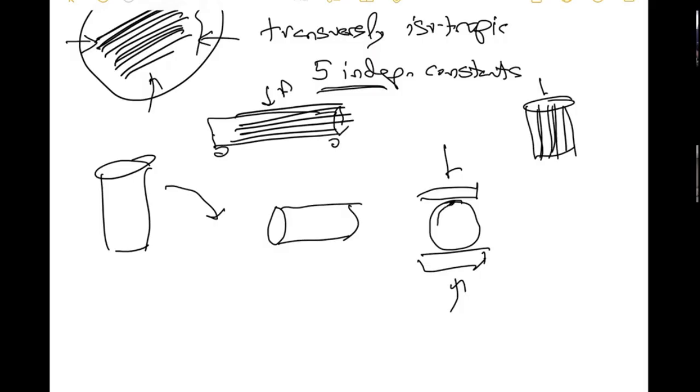So you end up getting the forces are flowing kind of like this. And so the result is you can solve the theory of elasticity problem, assuming that this has an E and a nu. Remember, I said if it's linear elastic isotropic, once you know E and nu, you know everything about how it's going to deform. And it turns out that along this line, you get a pretty high tension force.